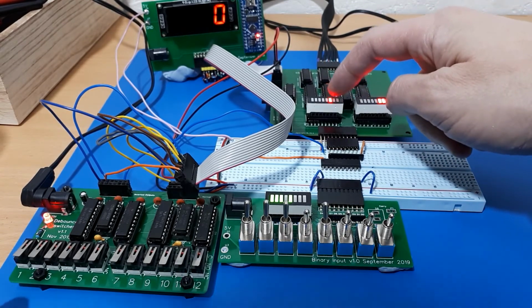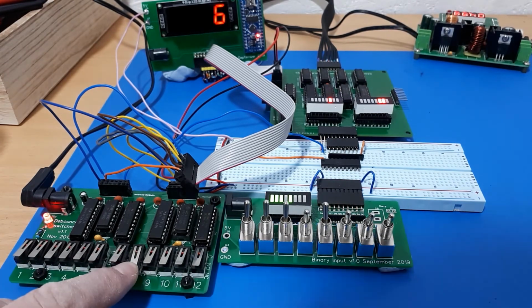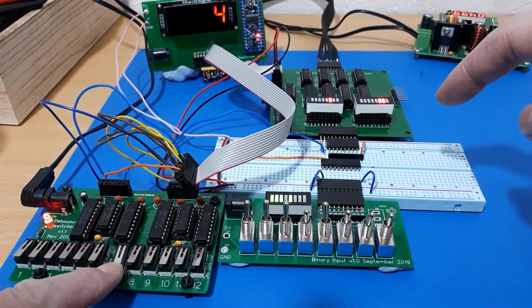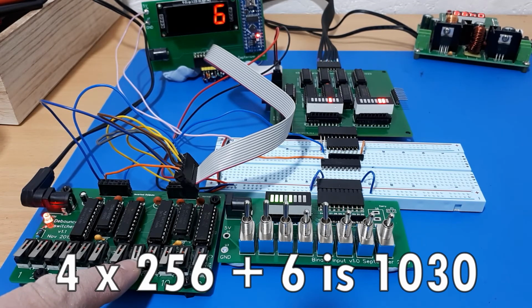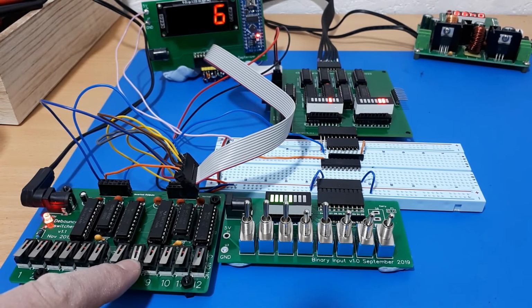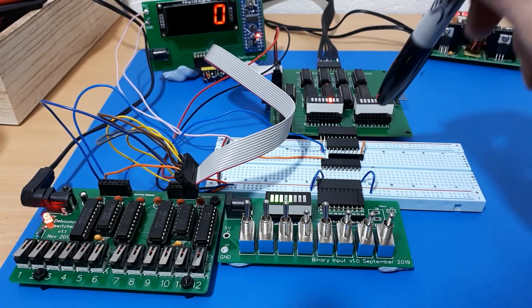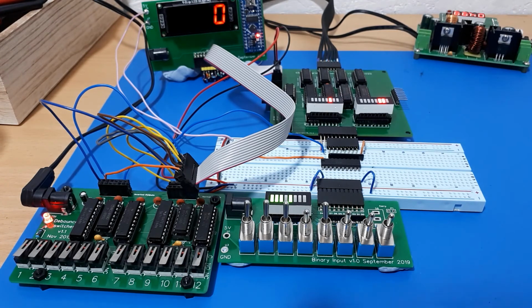So if we publish the high section, sorry, publish is 7. Right, so we've got 4 in there, and we've got 6 in there. So 4 times 256 is 1,024, plus 6 is 1,030. Exactly, so we've got 1,030 in the program counter. So I've managed to store a 16-bit number in the program counter. I've managed to increase it. I've managed to publish it back out again, and check that it works. And that is pretty much all the program counter does.